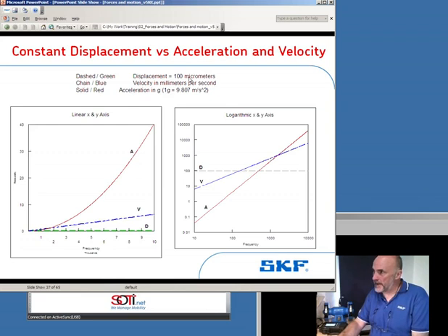My starting displacement is 100 microns, and that is just general vibration. If you put your finger on your engine block when it's not hot and it's just ticking over, the tingling sensation that you'll get on your finger will be about 100 microns.